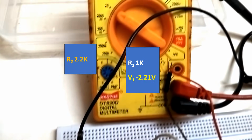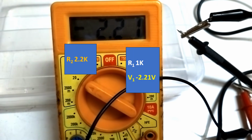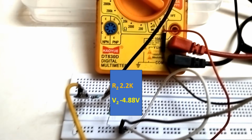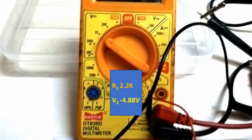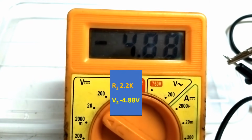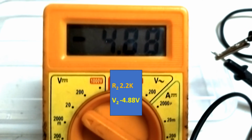Now I have changed the second resistor from 1 kilo ohm to 2.2 kilo ohms. So you can see that the potential difference across the first 1 kilo ohm resistor has come down to 2.21, that is minus 2.21 volts. As expected, the potential difference across the second one is more than double, minus 4.88 volts. That's because the same current is flowing through all resistors and with the resistance more than doubled, you will have more than twice the potential difference across it.